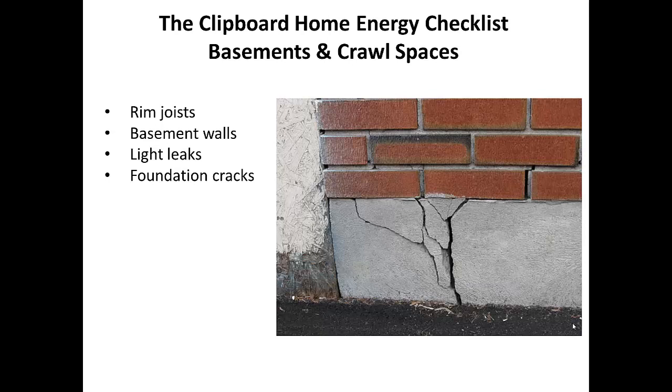Another thing to look at are cracks in the foundation. A lot of times these cracks will go all the way through. Sometimes you need to get a professional to take a look at it. But if that crack goes all the way through, that's a ready-made place for air infiltration to come through, let alone water or other things. So those certainly need to be addressed.